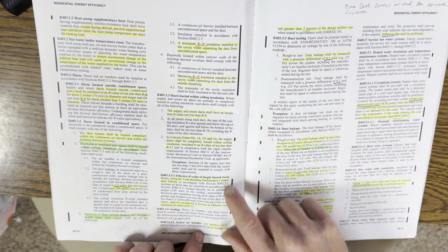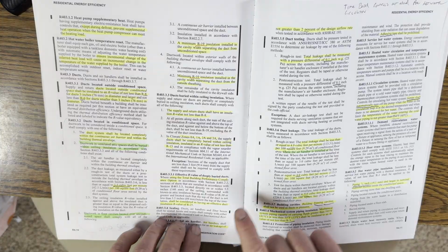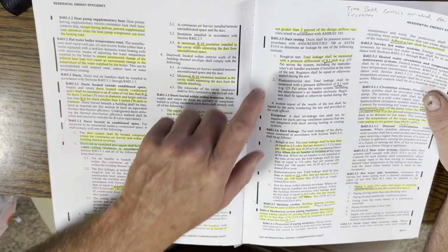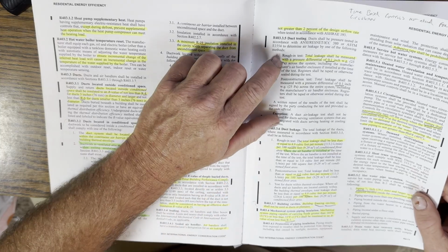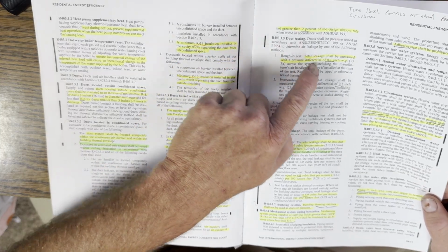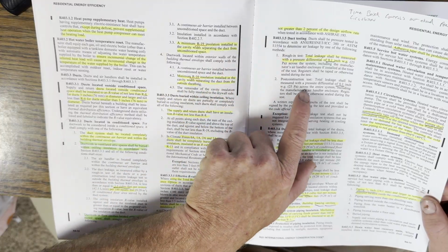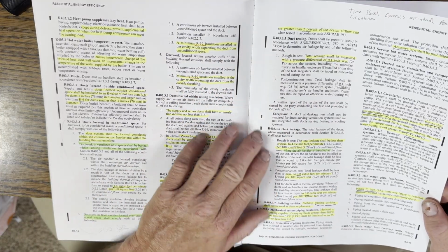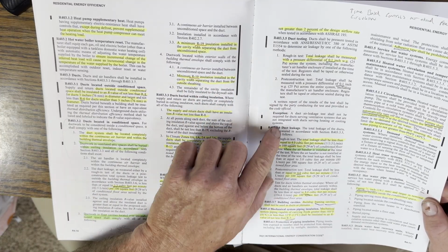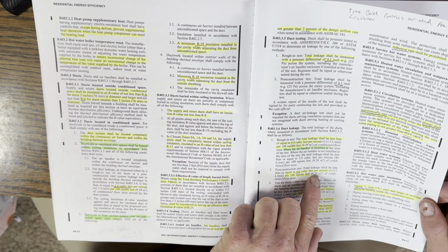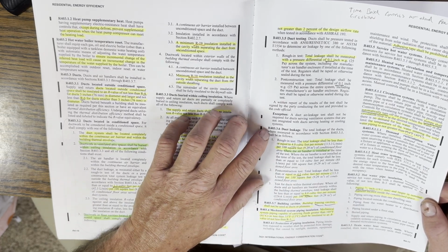Oh yeah, I was asked this. So new air handlers, what percent of the design airflow rate is allowed for leakage? It's 2%. That came right off the test. And then you have this, 0.1. Total leakage shall be measured here, rough and test, post-construction, 0.1. So you had those. I think you had one here too. I don't remember what it was. It was 4, I think. 4 cubic feet per minute under R403.3.6.